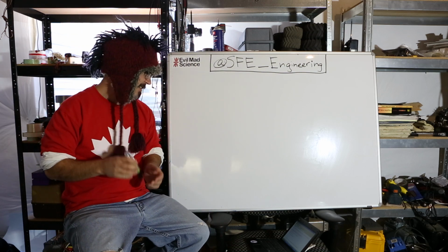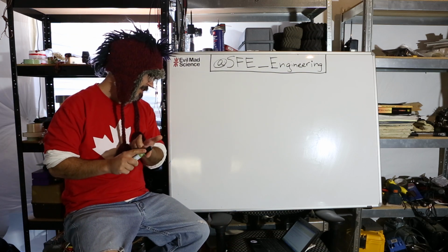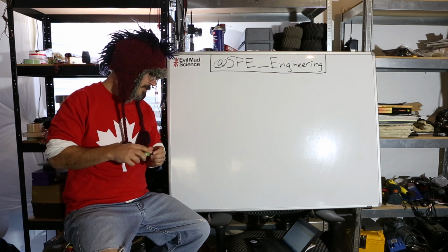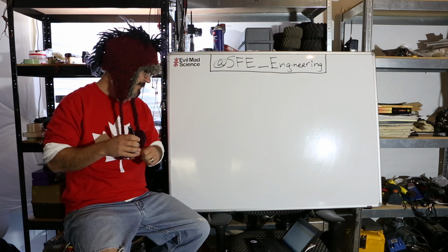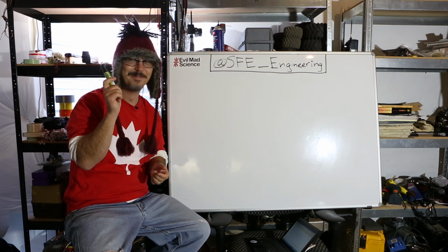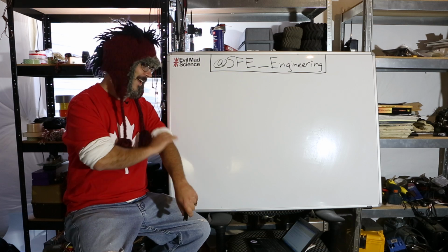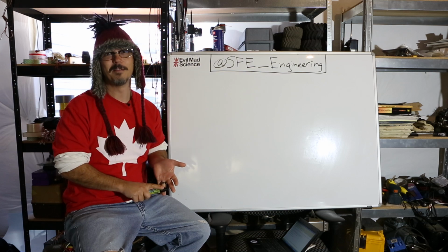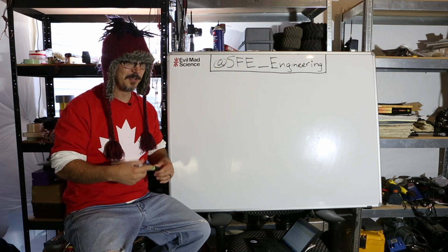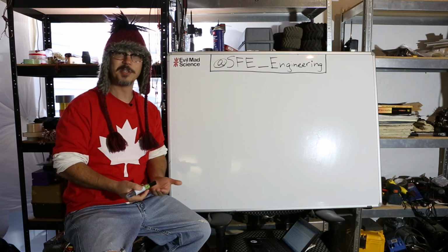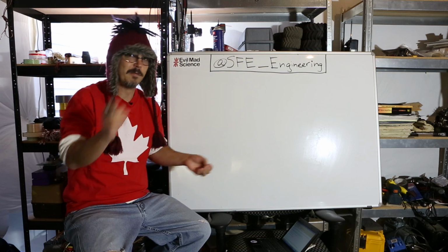Superflyer, coming to you! The first thing Superflyer asks about is through-hole via placement, optimization, and minimization on a two-layer board. The Eagle router loves to shuffle through holes between high current SOT23 MOSFETs. The first thing I will say is don't get victimized by a rogue auto router, man. If you want good results, you've got to do the work yourself. I guess some auto routers can be optimized to better reflect what you're looking for, but you're going to save a bunch of time by doing the layout yourself manually.